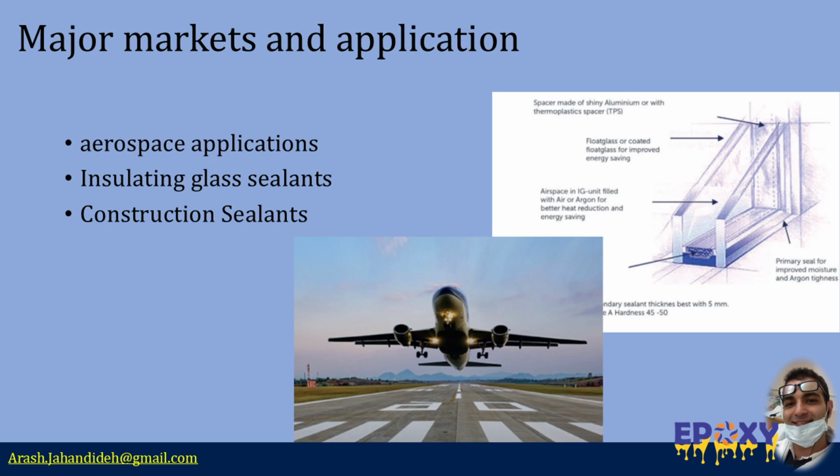These sealants must also meet a host of performance criteria, including resistance to water and UV light, durability across temperatures from -50 to almost 90 degrees Celsius, and strong adhesion to both glass and metal. Additionally, they must be easy to apply under industrial manufacturing conditions, making liquid polysulfides a preferred choice for IG manufacturers.